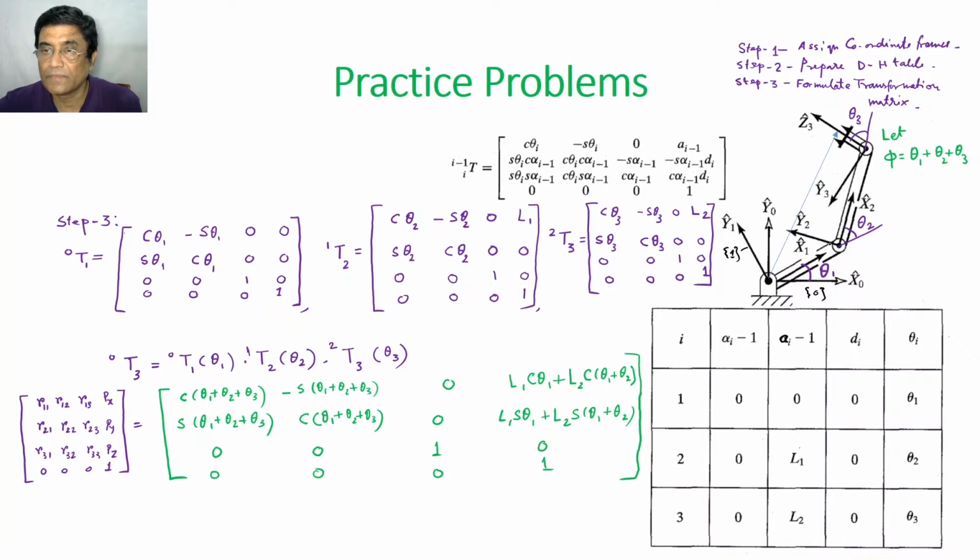So this is the 0th link. You get my point, right? You can also refer to our textbook, Craig's textbook, to see how to direct x. X will be directed towards the direction of the common normal. Common normal is characterized by the link length, and here it is planar, and all the z axes are perpendicular to the plane of the board. They are parallel. So anywhere you could figure this out, and I am pointing x in a convenient way in this direction.